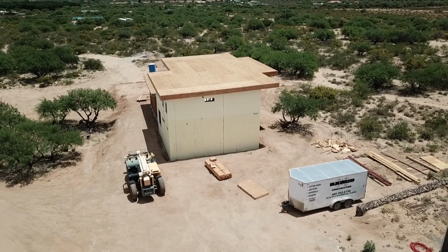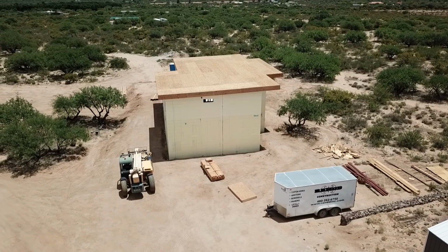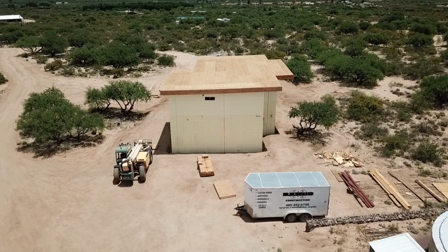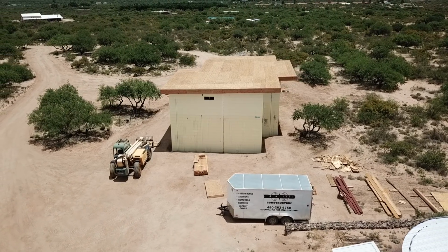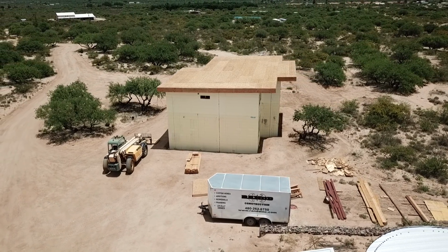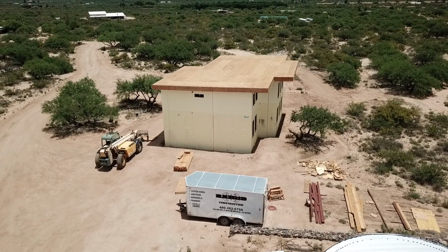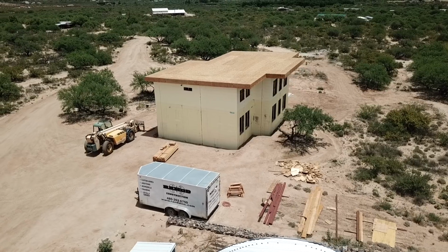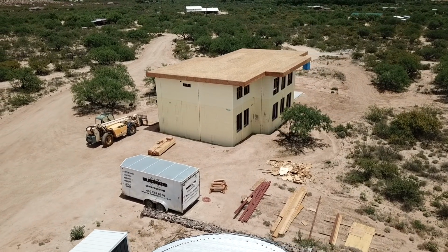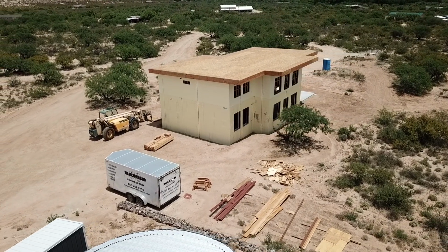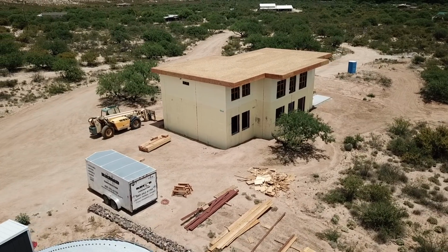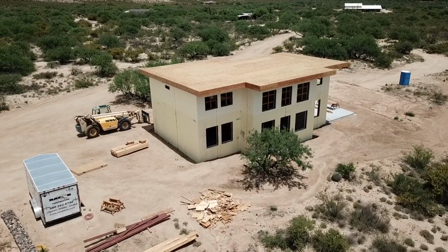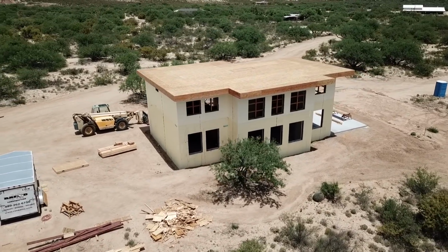Now this drone shot is showing the west side of our home, and you can see that there's only one little window in the upstairs bathroom, which will just give us some natural light in that bathroom. But we don't have any big windows on that west side because in the afternoon, when it is hottest here, you don't really want to be getting any solar gain through the west side of the house. Any rooms where that sun is getting in are going to probably get about 4 or 5 hours of solar gain through those windows, and it's going to make those rooms much warmer and most likely much more uncomfortable as well.